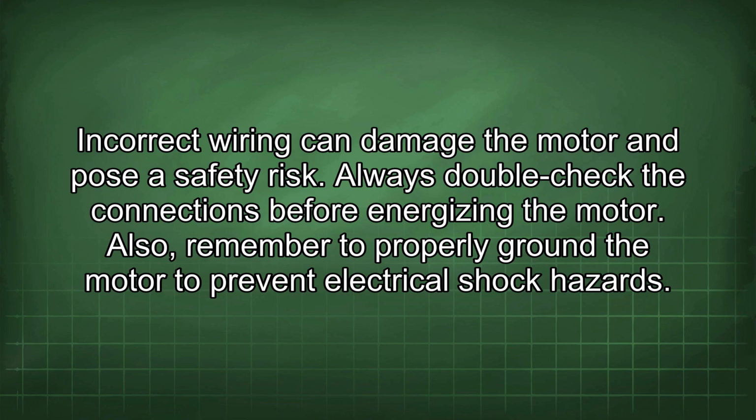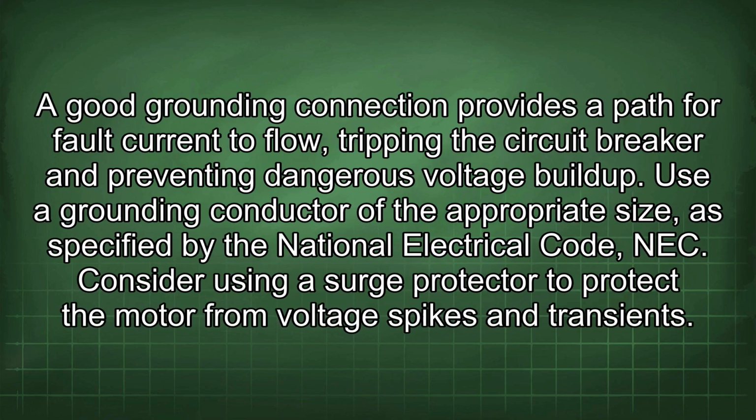Also, remember to properly ground the motor to prevent electrical shock hazards. A good grounding connection provides a path for fault current to flow, tripping the circuit breaker and preventing dangerous voltage buildup. Use a grounding conductor of the appropriate size, as specified by the National Electrical Code (NEC).